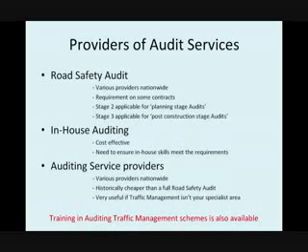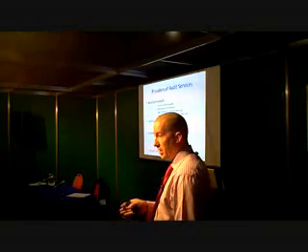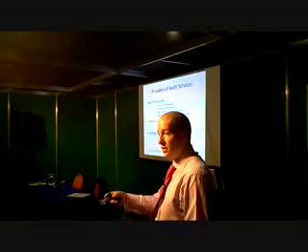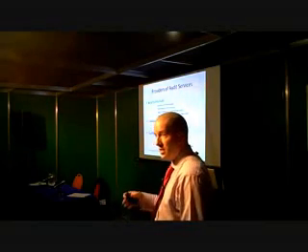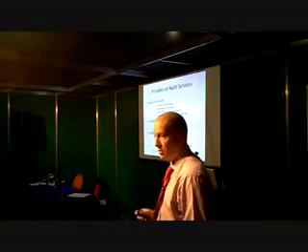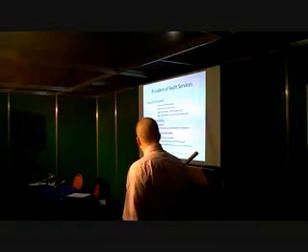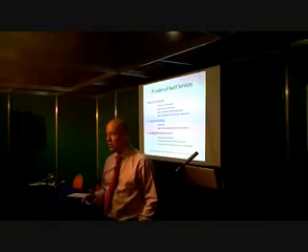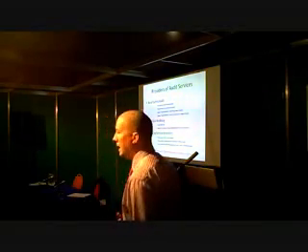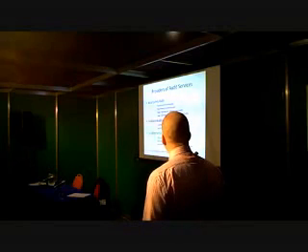Stage 3, it says within the road safety audit guidelines, is still applicable to temporary traffic management. And from the way it reads, I would conclude that it's for post-construction stage audits. For instance, where you've altered the permanent road layout to facilitate the temporary traffic management works, thus needing to put it back to what was the permanent standard after you've finished your works, an audit would generally take place to confirm it is now up to standards. So that's where this stage 3 road safety audit would come in. But for the actual construction stage, there's no formalised process within any legislation that's actually applicable at the moment.